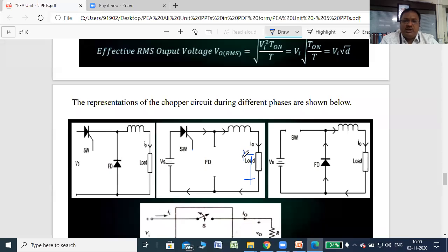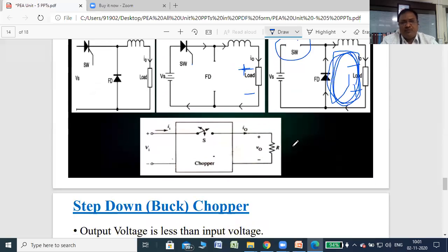It stores the energy in its magnetic field with the polarity positive upper, negative lower. Then whenever the switch is off, in the third figure, the energy stored across the inductor gets its polarity reversed. So the anode is positive, so current flows through the anode, then the inductive load and so on. So the output current is constant, but the output voltage is equal to 0 because the switch is off, right?